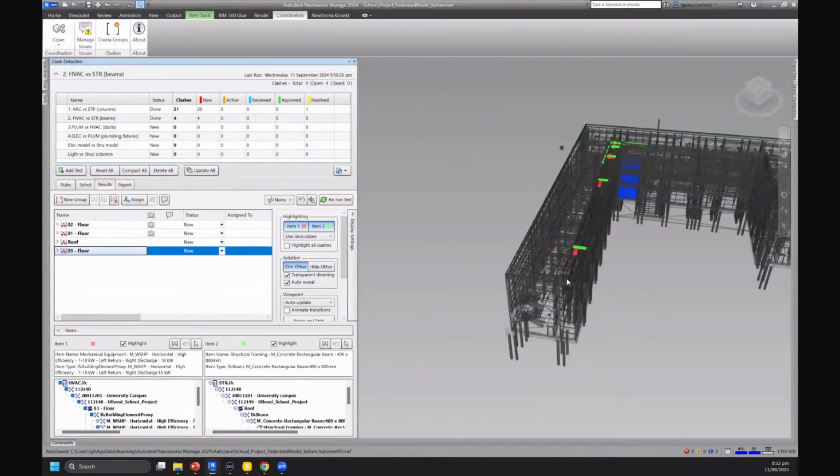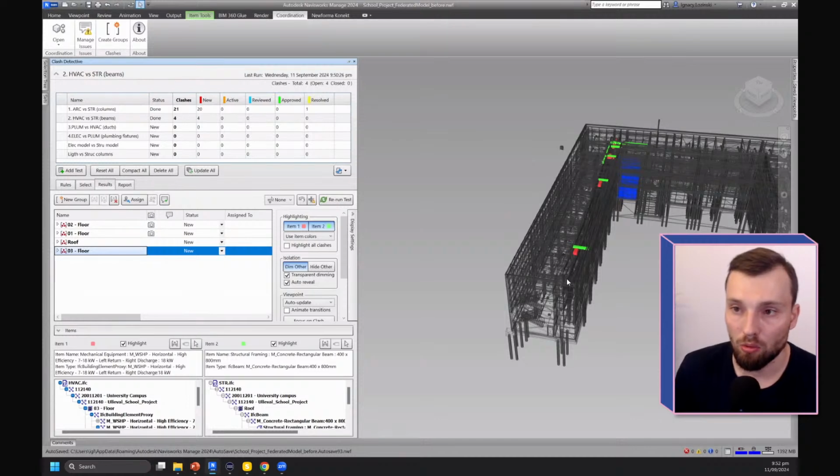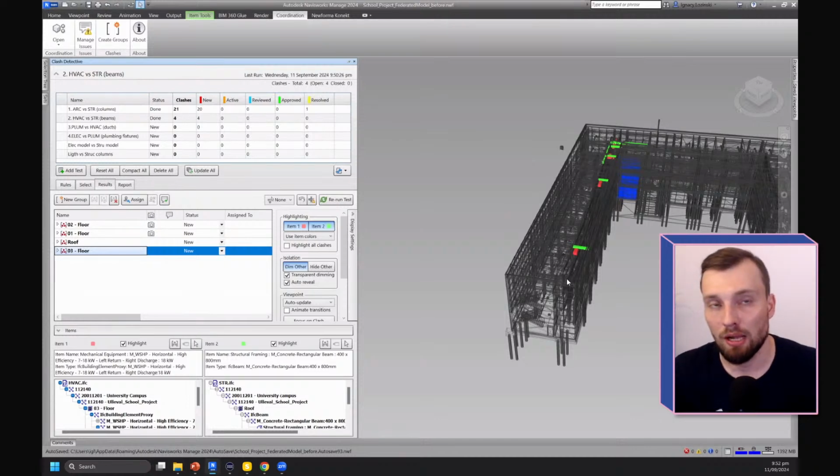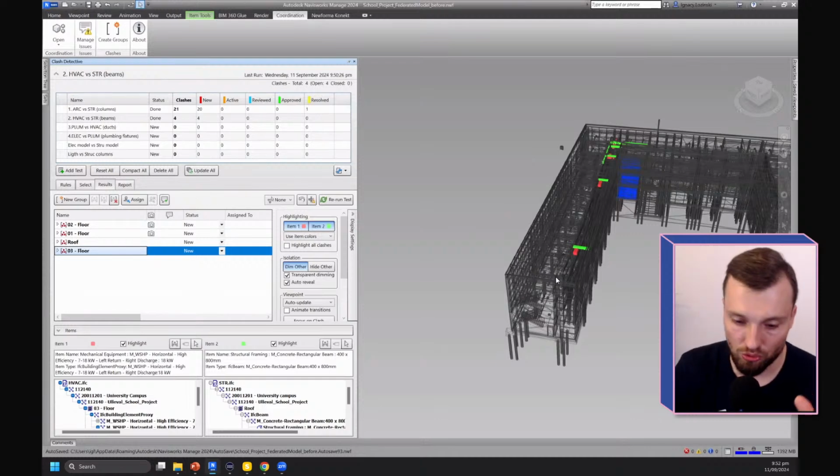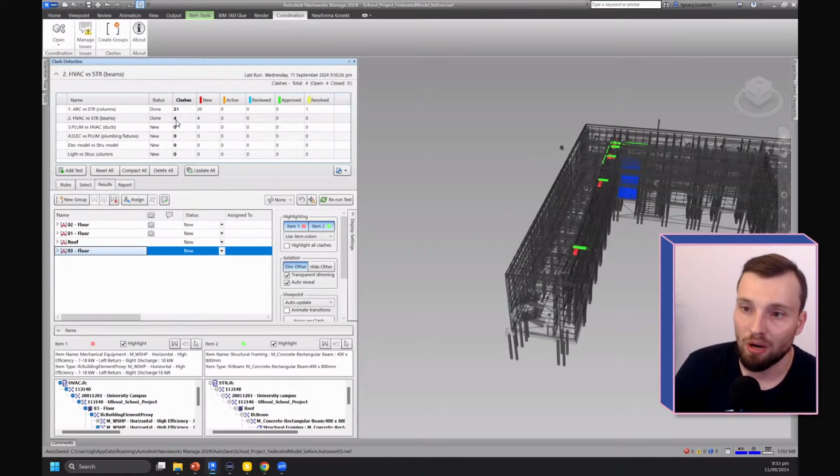So taking everything into consideration when you are working with Navisworks, first of all, you need to be very specific when it comes to creation of clash tests. Take into consideration the clash matrix concept and a system hierarchy concept. Clashes of architectural versus structural most probably have higher priority than electrical versus plumbing issues. And also, second, please group things, because you are not going to go through 180 issues, but right now we have 4 issues.